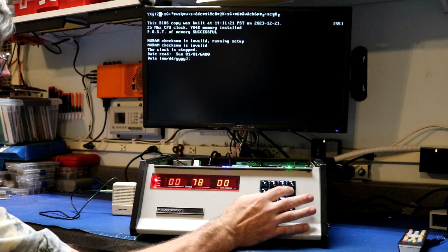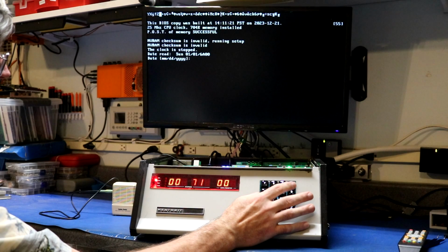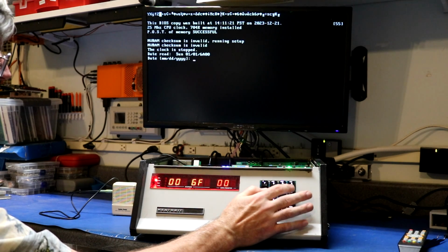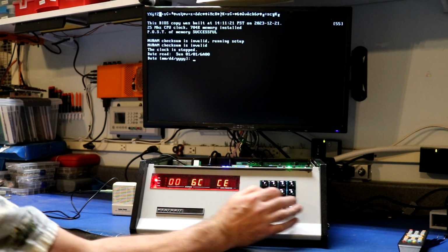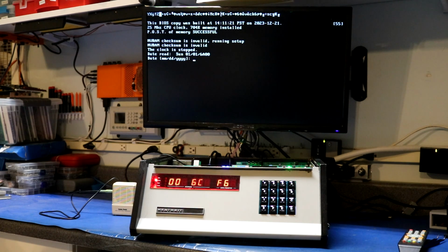See, lots of stuff goes by. And get down to about 6. Oh, there's 1, 2, 3, 4. That's like the warm boot signal. 6C, and we run into another counter. This one is actually part of the standard BIOS, and this is the 18.2 times a second counter, which I think all PC compatibles have. It's your standard counter sitting down there.